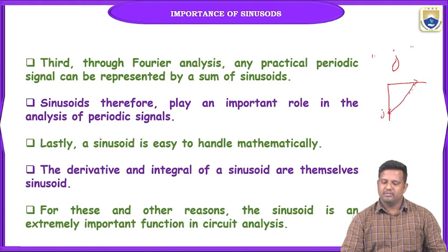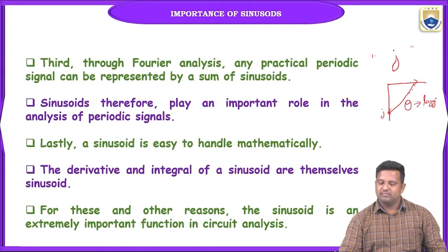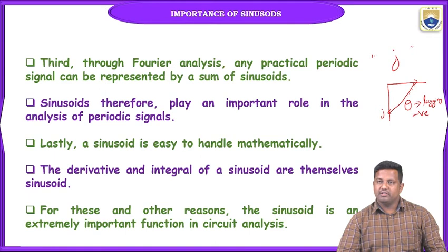So here is the J operator. We will see in the graph theory that when vectors rotate in the clockwise direction by making an angle theta, these thetas are called lagging in nature, indicated with a negative symbol. So the J operator having unity magnitude and revolving 90 degrees is a property of the J operator.